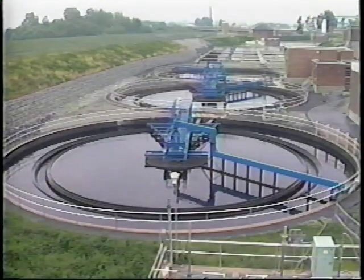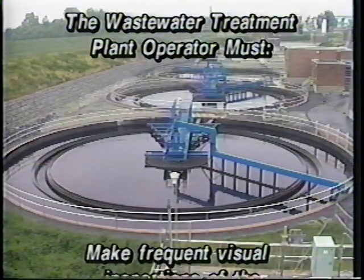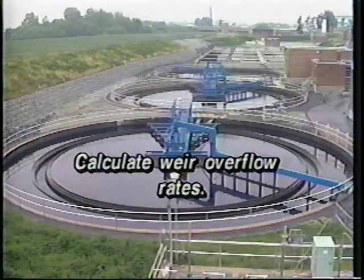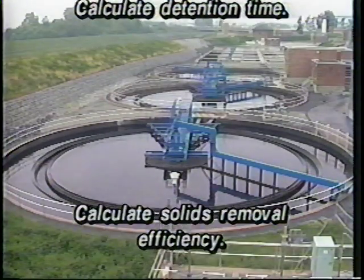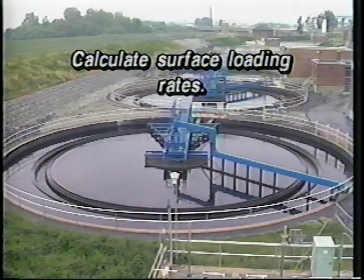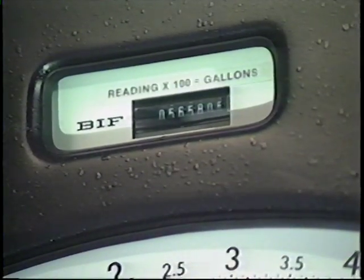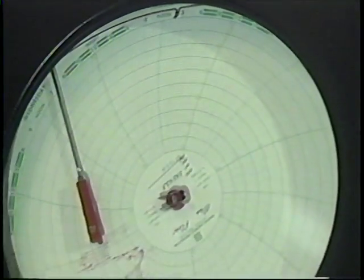In order to ensure proper operation of clarifiers, the wastewater treatment plant operator must make frequent visual inspections of the clarifier units, calculate the flow through the unit, calculate weir overflow rates, calculate detention time, calculate solids removal efficiency, calculate surface loading rates, and calculate solids removed from the clarifier. In making these calculations, the operators should account for the variations that occur in daily, weekly, or seasonal flow conditions.